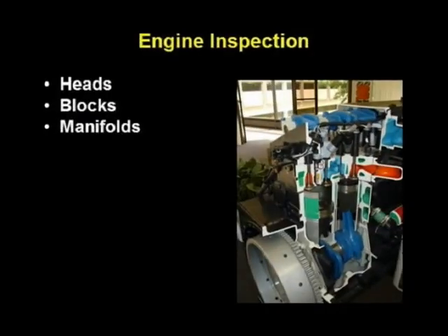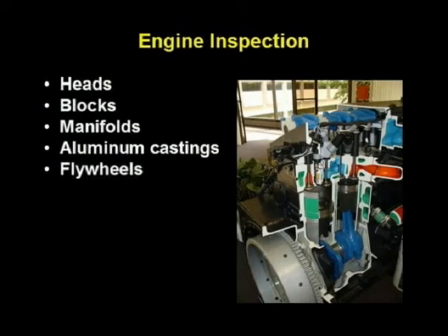X-ray CAT scans, or computed axial tomography, is used to check the interior dimensions of new castings and to reverse engineer other castings of interest. Other castings have been inspected as well. A flexible ultraviolet light borescope was used to perform fluorescent penetrant inspection inside exhaust manifolds for cracks. Radiographic inspection has been used for 100% inspection of aluminum compression brake castings. Radiographic inspection is performed to qualify new vendors for flywheel production.